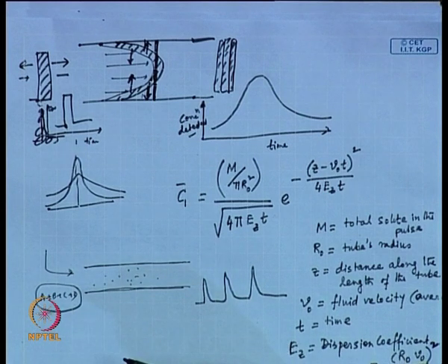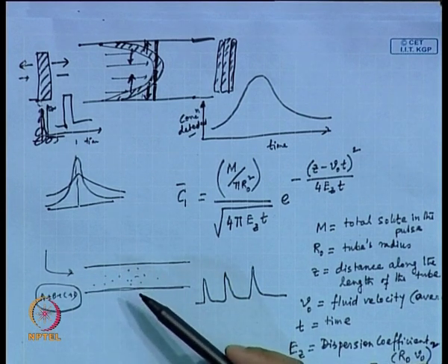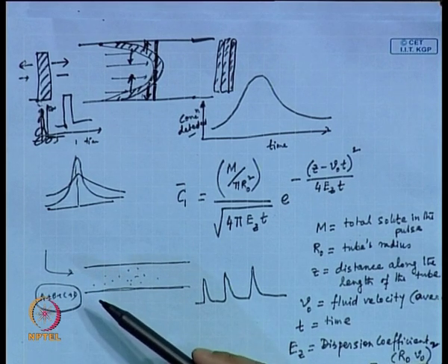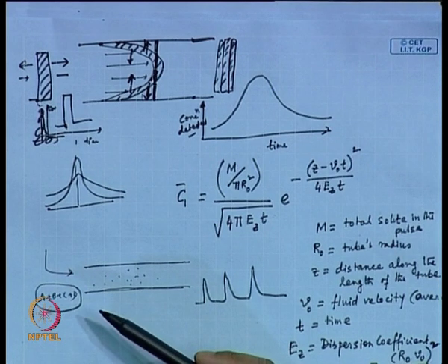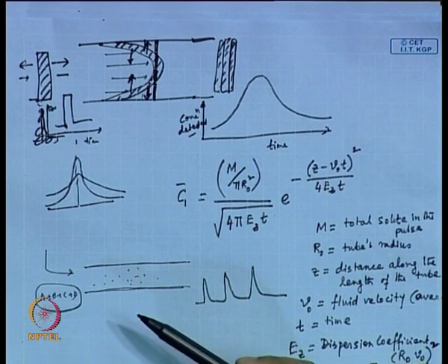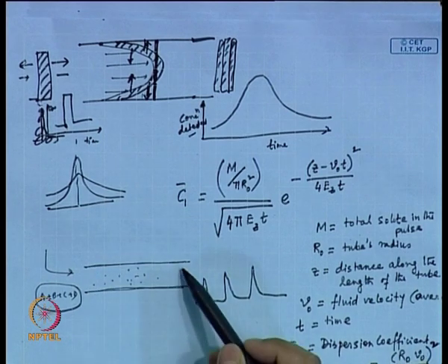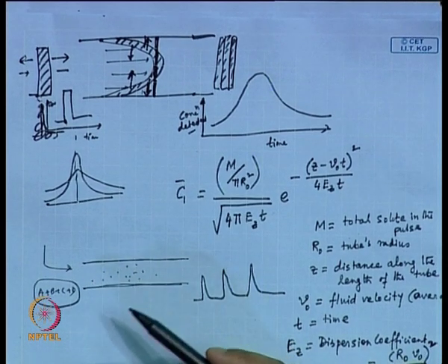Now, in a microscale process, you do not expect the beads to be there. It is accomplished in two ways. One is you have a microchannel with a wall coated with adsorbent, so the wall acts as an adsorbent. Or you have a monolith, because such a small bed is not very common. A monolith structure is more like a honeycomb, already inbuilt. The entire passages are built in an integrated structure. It is not like you take a tube and then take a pack of beads and fill it there.